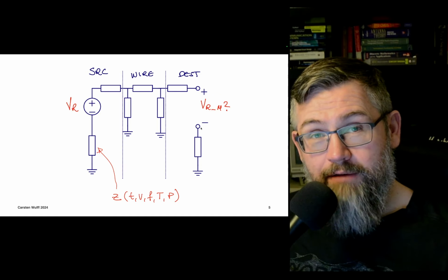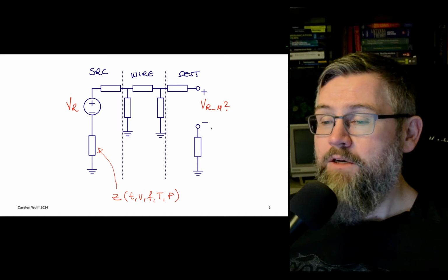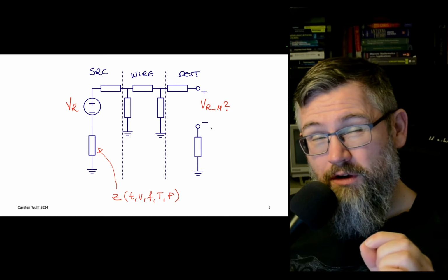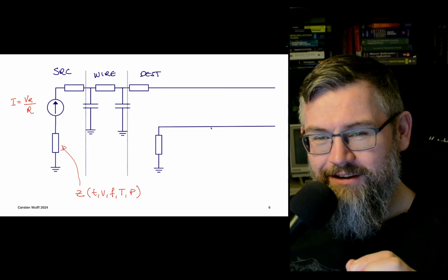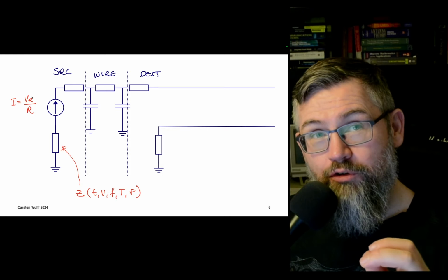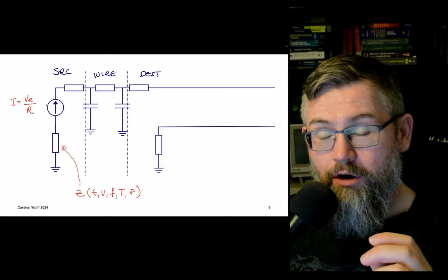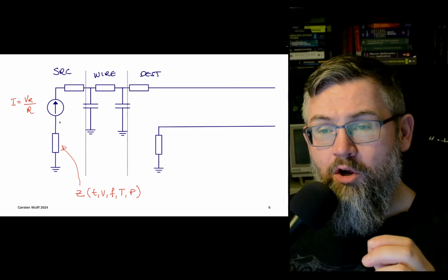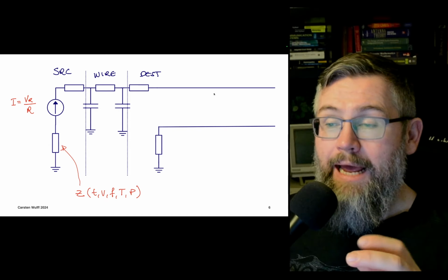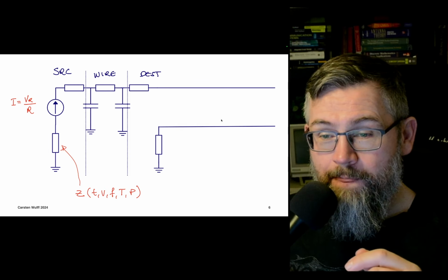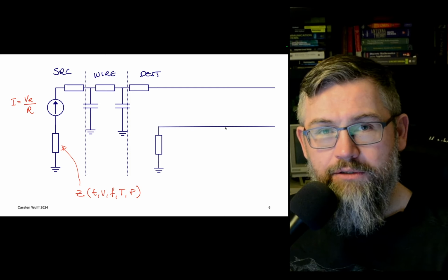Now, definitely you don't necessarily have the same voltage, and you also have a potential for noise injection into your reference. So that means if you actually want to distribute references on a chip, quite often it's better to do it in the current domain. So what we can do is convert our known reference voltage into a current locally. Now, the current will flow through the ground impedance, but as long as we don't lose any current in the wire from the source to the destination, and we put a resistor between the two wires here, then we can actually know the current in that resistor.